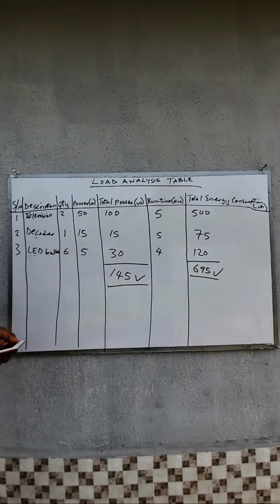Ask him how many appliances he has. Where many of them have issues is maybe in a hotel. You want to install a solar system in a hotel. Remember, in the hotel, you have water heaters. Some of them are rated at 3,000 watts, and you're having like 100 or 200 rooms. It means you're having about 100 to 200 water heaters. And if you're having 50 guests.